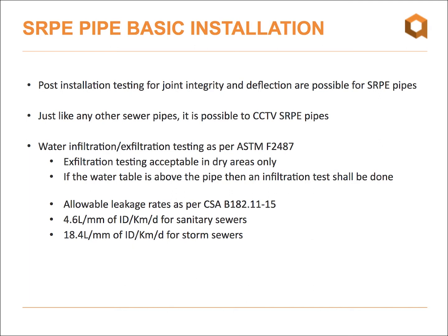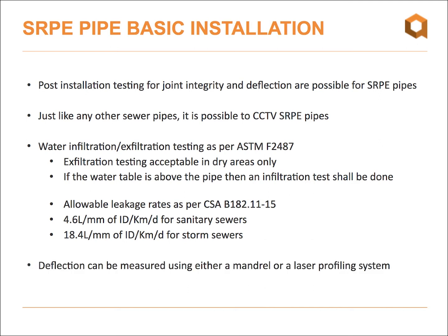day for storm sewers. And finally, this being classified as a flexible pipe, there might be limited deflection, and this can be measured either by using a mandrel or by using these new laser profiling systems that have gained more presence in the field.